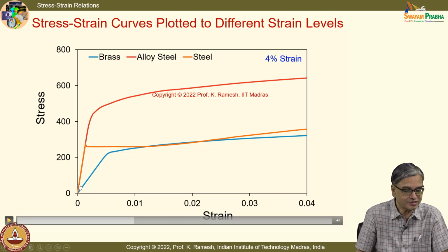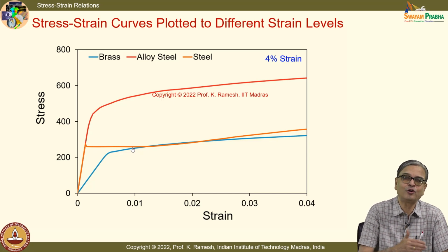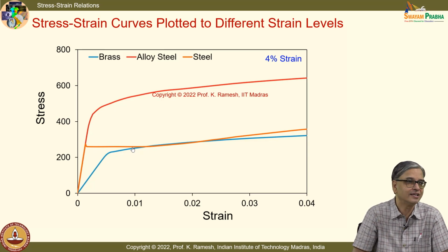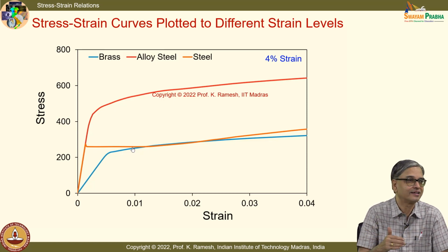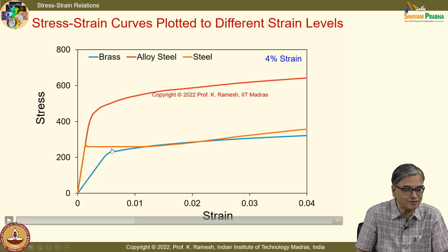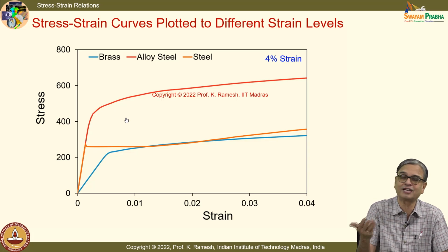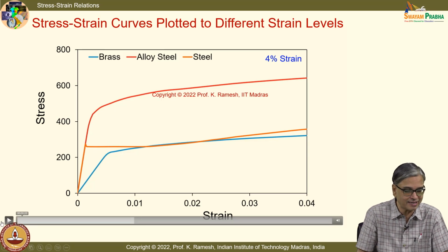Here again, you are able to see I have a straight line portion and a horizontal portion. This is a very celebrated approximation people do. The moment they want to enter into plasticity, they don't want to analyze plasticity in all its complexities. People would like to have elastic and plastic, perfectly plastic. That's the way they look at it. Because you have a graph which has horizontal, and because the graph is increasing here, they have to come out and distinguish what is that happening. That is why I coin that as strain hardening. You know, terminologies also come like that.